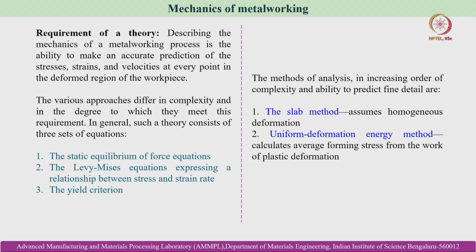Okay. So, the requirement of a theory describing the mechanics of a metalworking process is the ability to make an accurate prediction of the stresses, strains and velocities at every point in the deformed region of the workpiece. The various approaches differ in complexity and in the degrees to which they meet this requirement. In general, such a theory consists of three sets of equations: the static equilibrium of force equations, the Levy-Mises equations expressing a relationship between stress and the strain rate, and the yield criterion.